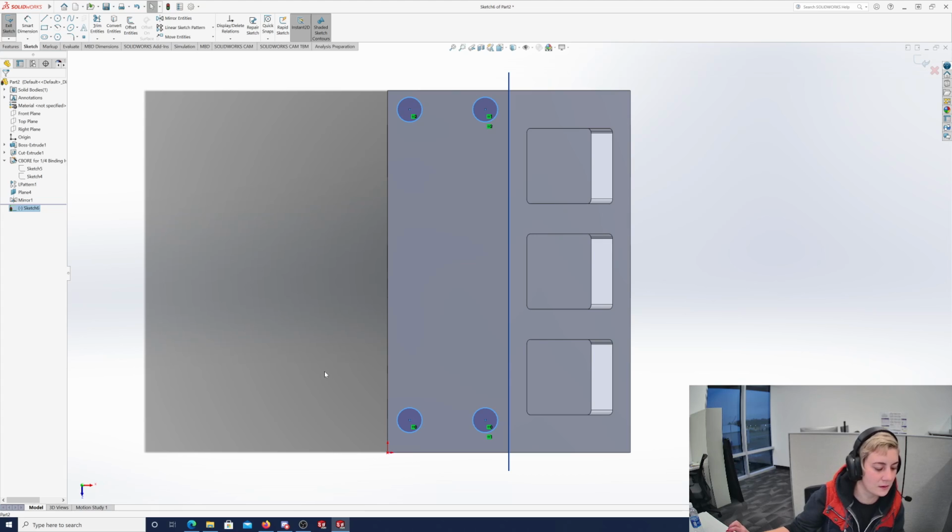That might be because for your direction, it said select edge one. If for some reason you clicked a vertical edge instead of the horizontal edge, you might have selected it by mistake. It's hard to tell after you do it. So just go in there, delete whatever's in that box, and then click that bottom horizontal edge to make sure you've got the right one. Does that make sense?